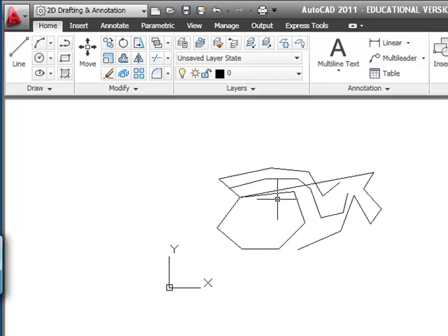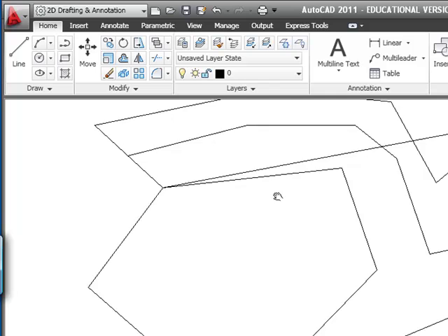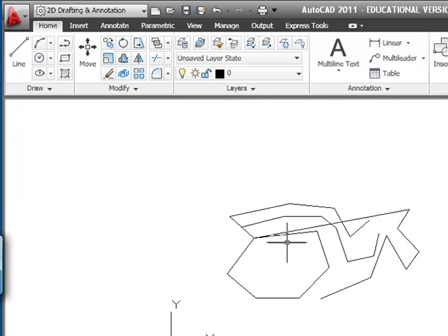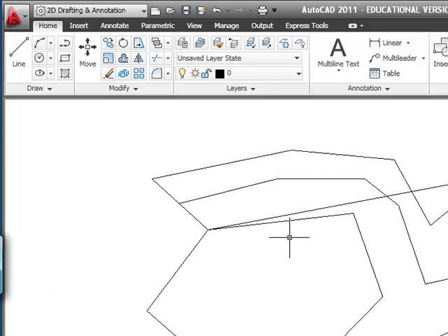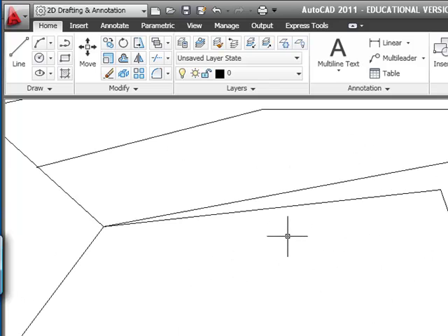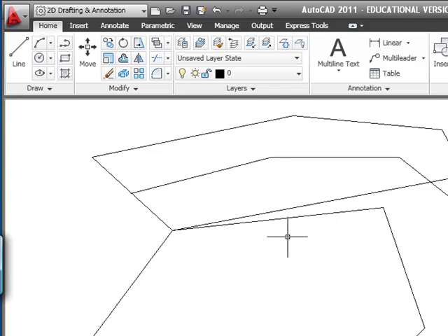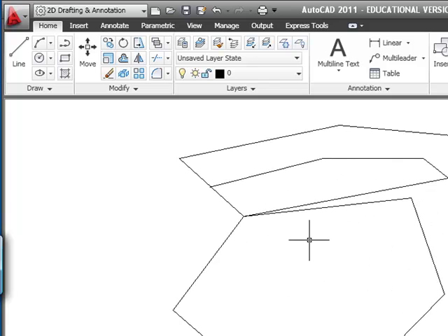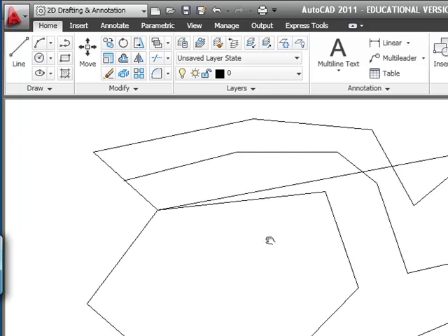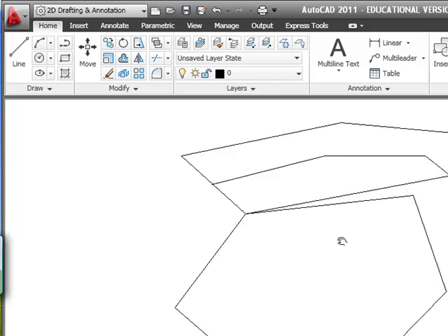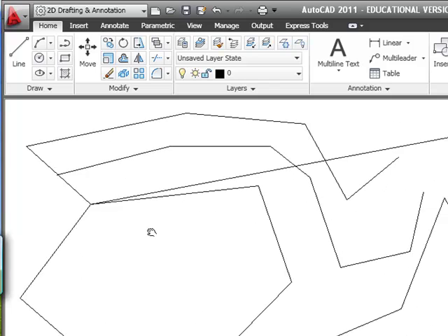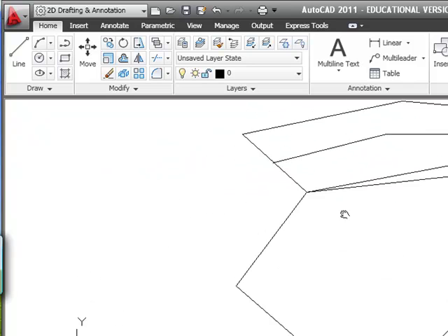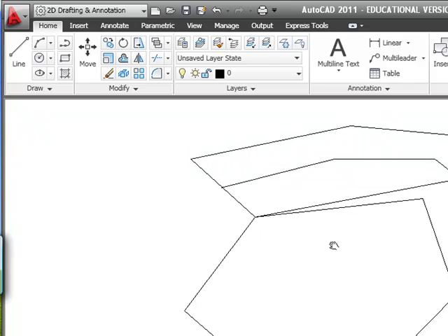Now there's a scroll wheel on your device that also facilitates zooming in and out of an object. So if you turn your scroll wheel, that will be similar to having selected that zoom. It's a little bit more efficient than that little zoom; real-time zoom is what they call that. Now I can also pan by taking my scroll wheel and pressing on it, and of course I'm able to move my object side to side or top to bottom, similar to moving it on my desktop.